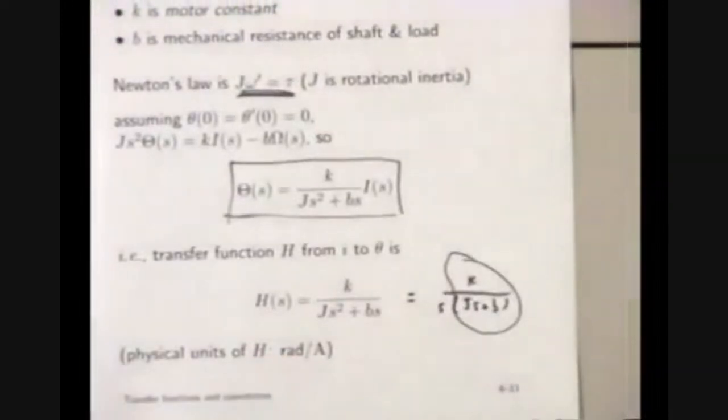And you'd say, well, there's some mechanical damping, and when I put the current on it, the speed of the motor doesn't instantly speed up. It takes some time. Okay? Then there's the 1 over s term, and they'd say, what's that? And I'd say, oh, that's the integral. That's the one that relates the angular velocity of the shaft to the position.